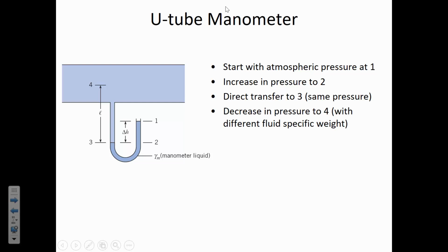That's right. So the delta H would be very tall for the typical pressures that we see in a pipe network. And then the other issue is that a piezometer is open to the atmosphere. And so dust, contamination, birds flying over it, it just isn't a safe way for potable water that's supposed to be clean.